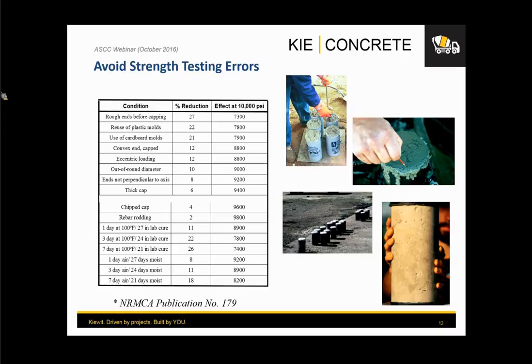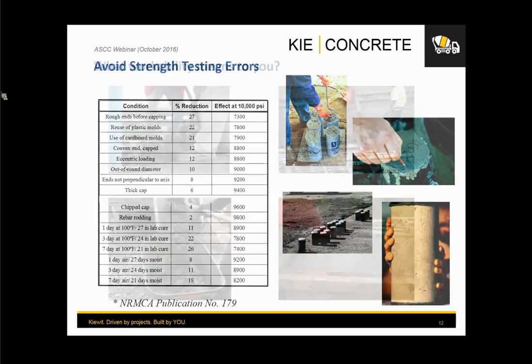And now everybody's going to get excited in the project, and your engineer of record is going to start requiring you to core your structures, right? And everybody, even the client, is going to start questioning the quality of that concrete in the structure, right? Those are the costs. That can result in stopping an operation for weeks. That can result in investigations that are not planned that are going to cost you a lot of money. So make sure that you obviously provide the right tools for those cylinders to be handled and cured properly so you can receive the right strength.